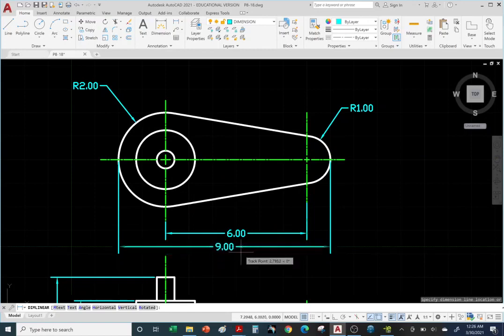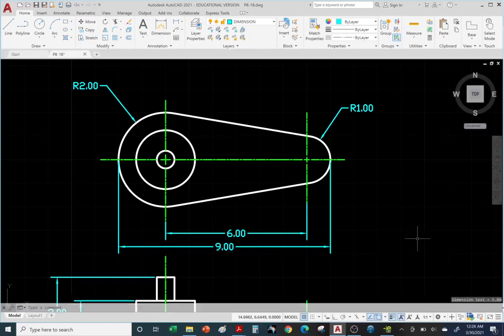But you're not allowed to have double dimensioning. If you can calculate it, you're not supposed to put it in there. So, for example, 9 inches can be calculated by adding 6 plus 1 plus 2 is 9. So it's considered double dimensioning. You're over dimensioning. So some can say, well, why don't we leave the 9 inside and take out the 6? Because the 6 in this case is more important than the 9.